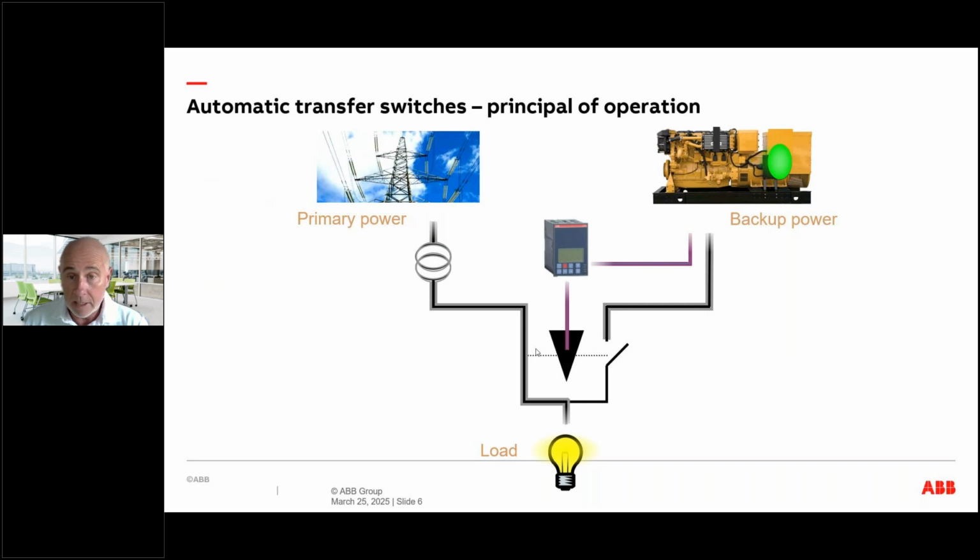So we're back to where we started, i.e. everything's back up and running as normal. The last thing the controller does is de-energize the backup power. That is the purpose and functionality of a transfer switch. As I said, this particular session is geared more at life safety, but the principles, as you can imagine, are exactly the same.